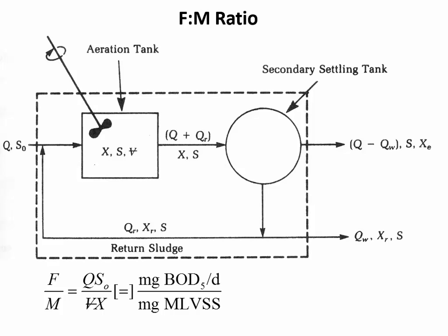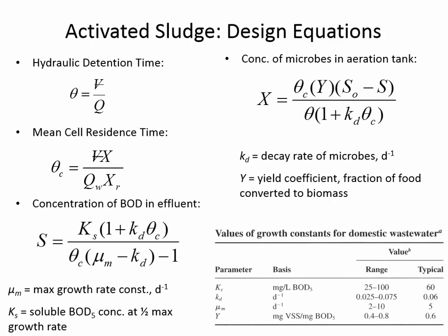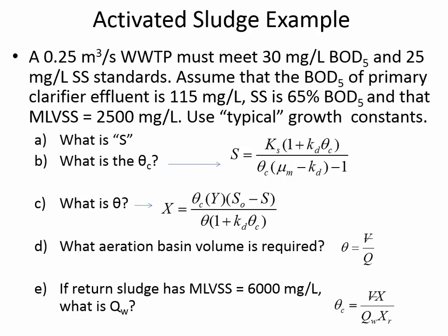The equations that we've just gone through today are a little bit of a simplification, assuming that X sub E is 0, assuming that the clarifier is 100% efficient at settling the solids downward and that none of the mixed liquor is getting into the effluent. When that's not the case, there are more complicated equations we can use, but generally those aren't needed at this level. All right.